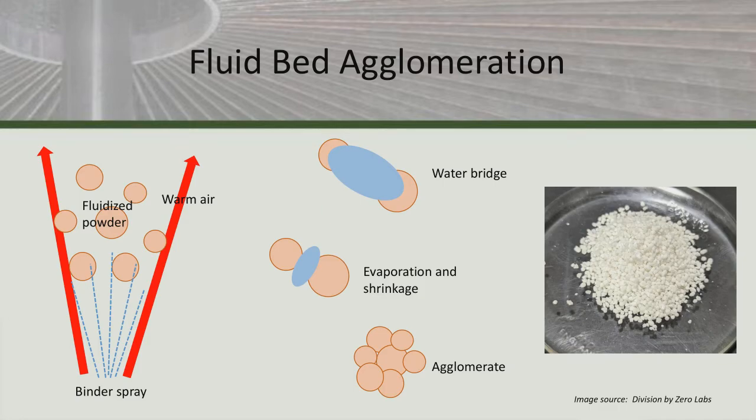And finally, I told you previously that some spray dried particles don't flow well, because their density is so low that they can't break surface tension. And they also won't dissolve very well. This is fixed through various processes known as instantization, which basically means we're making an instant powder. But one of the most effective methods is fluid bed agglomeration.